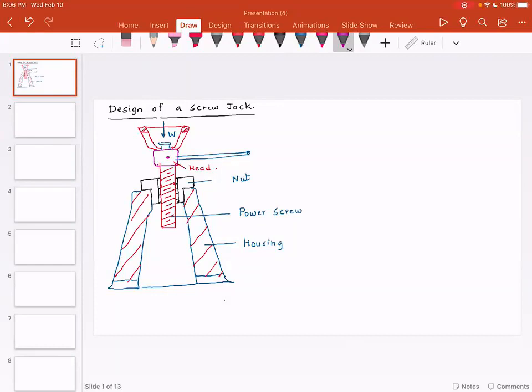For example, if you want to mold something or cast something, you need to have a certain amount of clearance. If you need to forge or form something, you need a certain minimum wall thickness. So these criteria come into the picture when we actually take this assembly and start manufacturing.